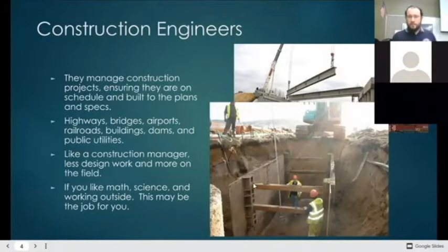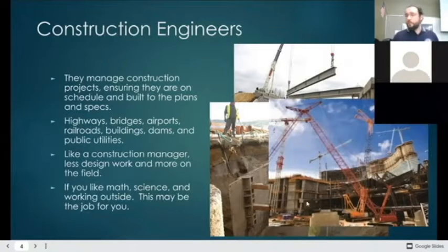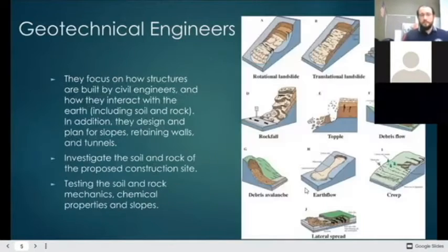Here, this is like, as I said, knowing different types of laws. That right there is so that if the land were to collapse, no one would get buried alive. After a certain depth, like 4 or 5 or 6 feet of digging a hole for putting in piping and stuff like that, you have to put in these support walls so that if there were a little landslide, the people in there would not get buried, because it's real dangerous. So there's a lot of safety stuff like that. Large projects like this might have a construction engineer on site all the time to inspect and make sure everything is being done correctly.